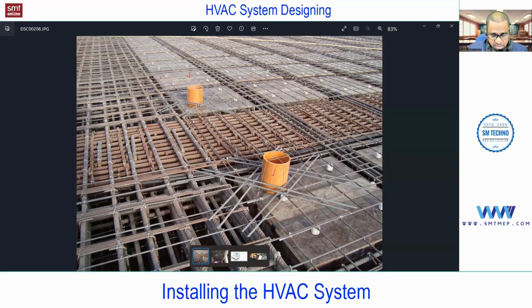But initially, at the design stage, if you coordinate, definitely they will design the structure accordingly, considering the openings for these pipes, because you see, this much of the material is lost in the slab, so they will design the slab accordingly. Similarly, for beams and columns, if you ask for pipe sleeves, they will design the structure accordingly. So at the design stage, yes, it is totally accepted and possible. But later, opening is not allowed, except in some special cases, and that too for small ones.